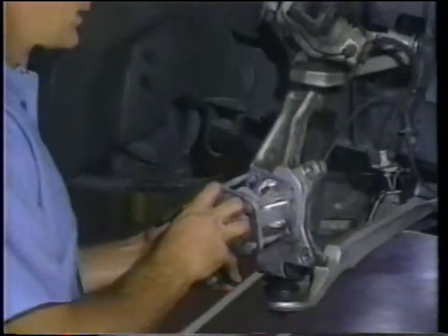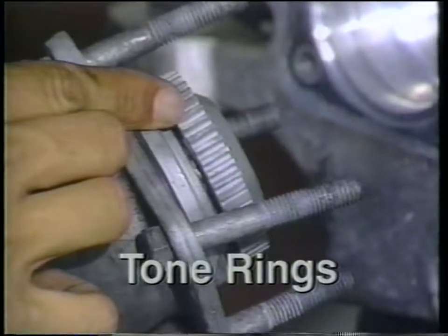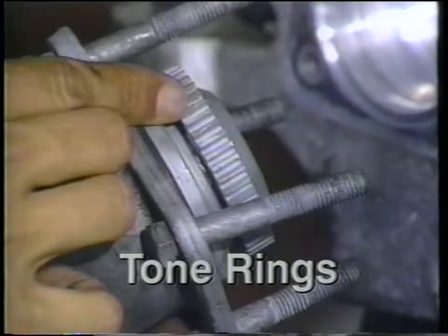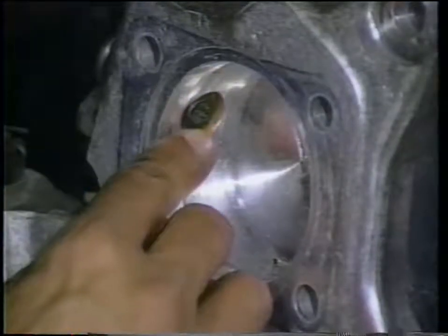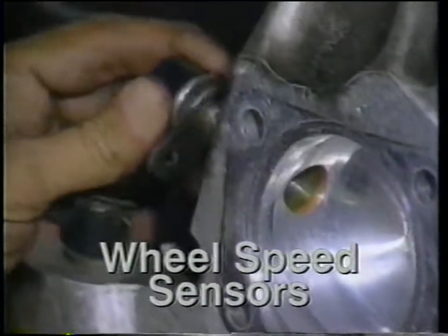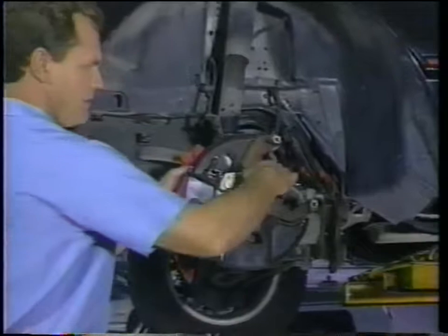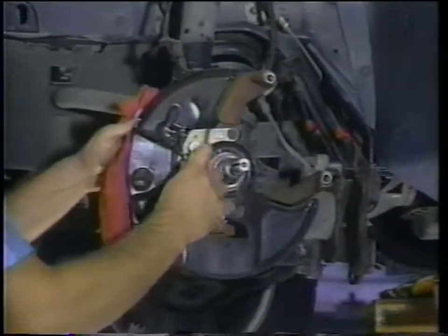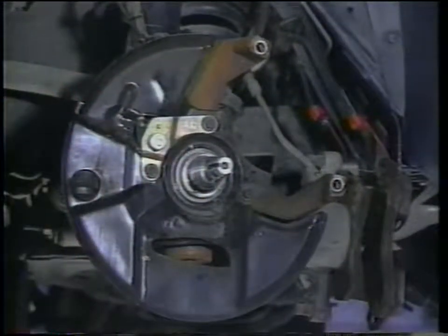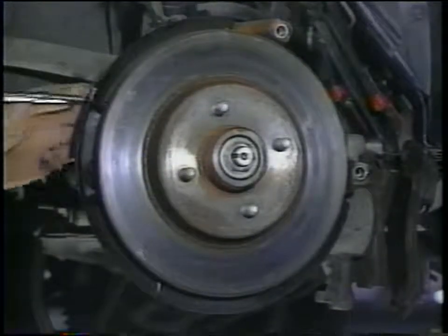The Bosch 2 consists of toothed tone rings, which, depending on the vehicle, can be located at each wheel or at each front wheel and on the rear axle or differential. There are also 3 or 4 corresponding wheel speed sensors, depending on whether the vehicle has 3 or 4 ABS channels. The very small distance between the sensor and wheel teeth is called the air gap. This can be adjusted on some vehicles, and on others it's set at the factory.